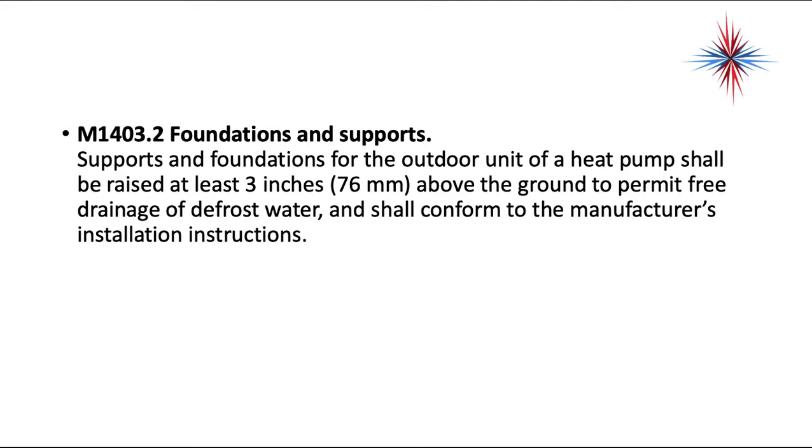Foundation and supports for outdoor installations of a heat pump shall be raised at least 3 inches above the ground to permit free drainage of defrost water and shall conform to the manufacturer's recommended installation instructions. Depending on where you are in the country, this code will vary.